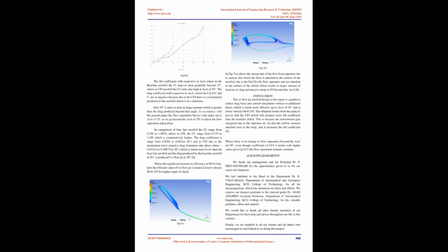The CL ranges from 0.356 to 1.0076, whereas in CFJ the CL ranges from 0.374 to 1.105, which is comparatively higher. The drag coefficient ranges from 0.0204 to 0.401 at 20 degrees, and in CFJ, due to the momentum force, negative drag formation takes place, from 0.03314 to